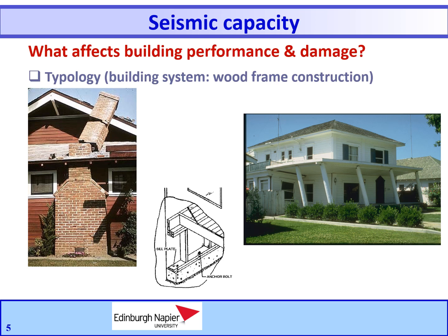Where the problems start is where, for example, we have large openings that greatly reduce the area of walls available to resist lateral and gravity forces, or significant irregularities in plan that introduce large eccentricities that lead to significant torsional loading.